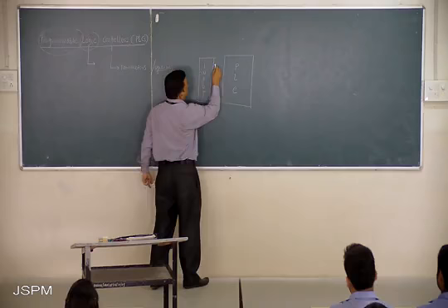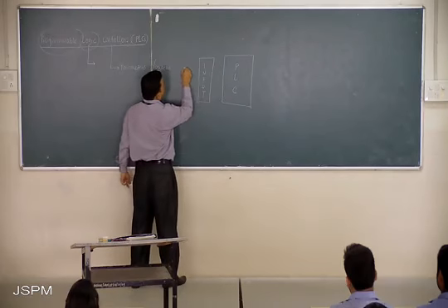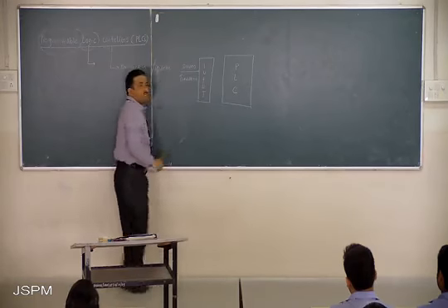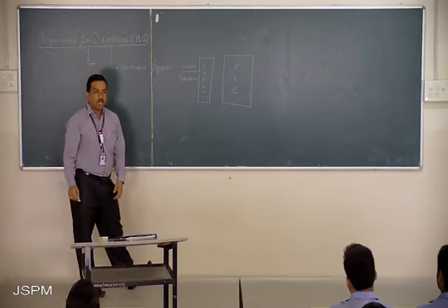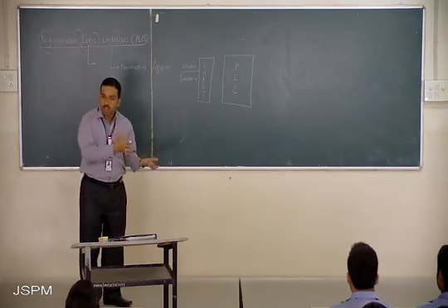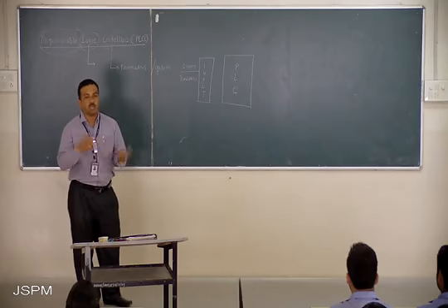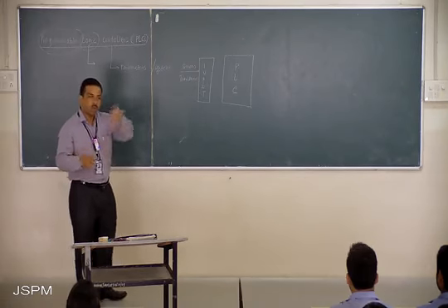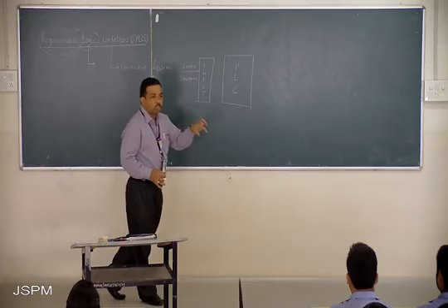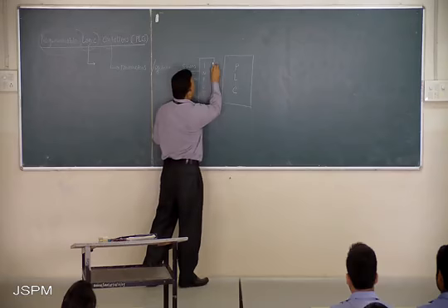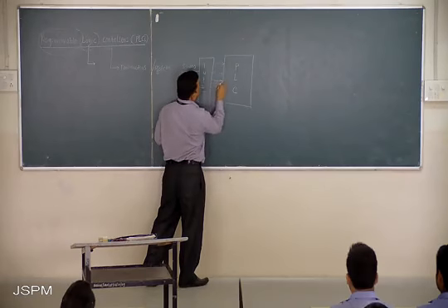Now what are these inputs? These inputs are nothing but your sensors and the transducers. Depending upon your requirement, whether you want to monitor the flow and control it, the velocity and control it, or the temperature and control it, whichever parameters you need to monitor, those particular sensors are going to work as an input, and all those sensors are coupled to a PLC.